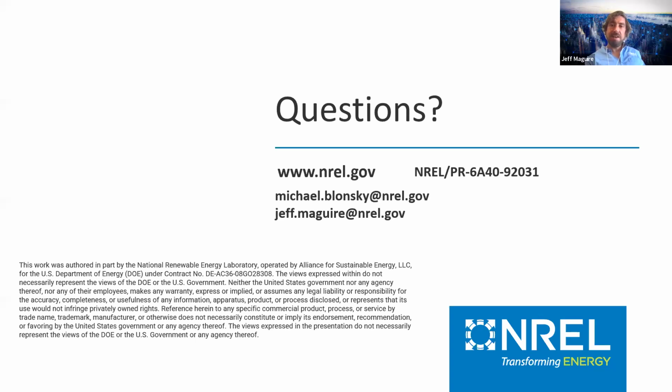I'm going to go back really quick, Michael. I want to talk to the ground coupling question too. Ron had asked about how we do ground coupling with slabs or basements. Right now, we're using the approach that used to be done in residential tools like BEopt, a 1D approach to estimate the more complex 3D heat transfer.